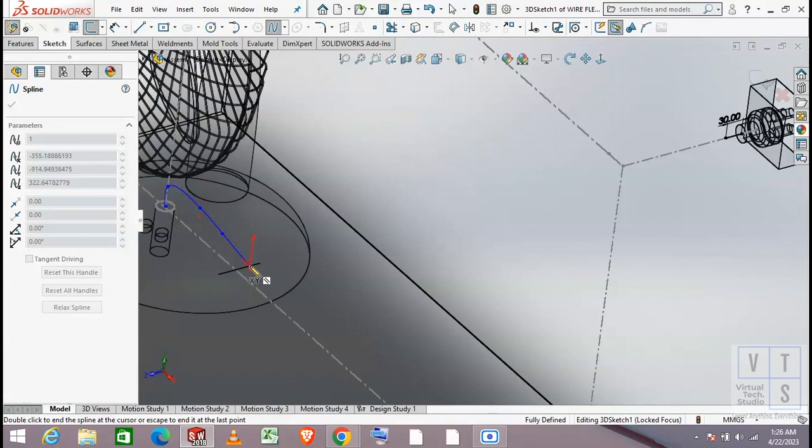Avoid any kind of relationships, except we will intentionally create some relations between our spline and the 3D guide sketch that we will delete later. Finish the sketch somewhere near the line just created.